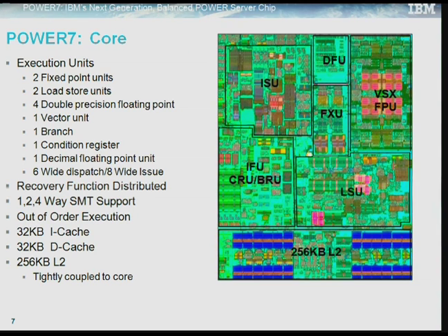Okay, let's take a look at the Power 7 core in a little more detail. If you look at the core, you can see in the center of the chip the 2 fixed point units. Those are aligned directly above the 2 load store unit pipes on the left side of the load store unit. The idea is we want those buses engineered directly to the load store unit. The second level translation is to the right of the load store unit.